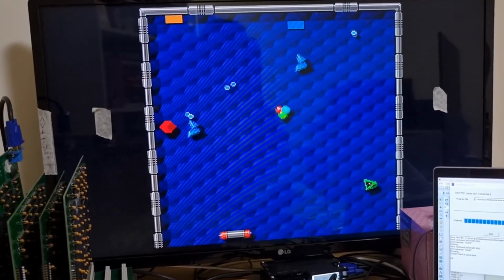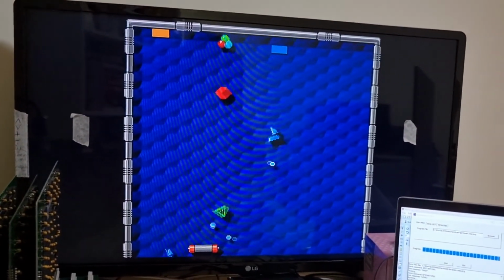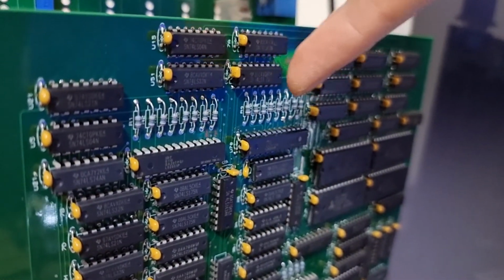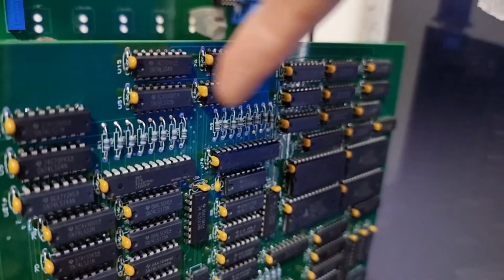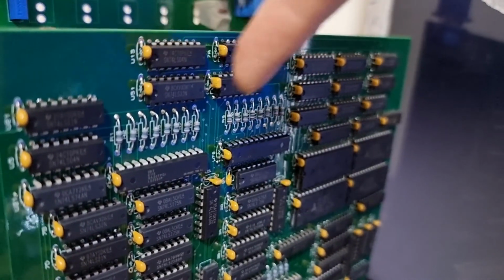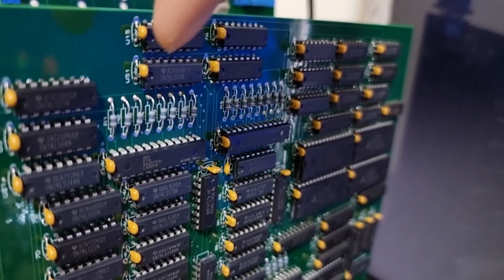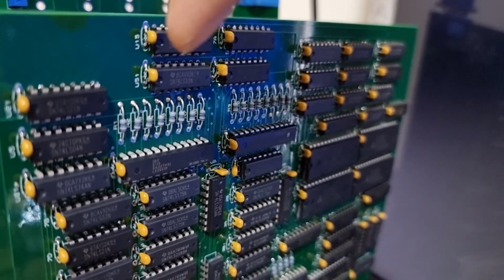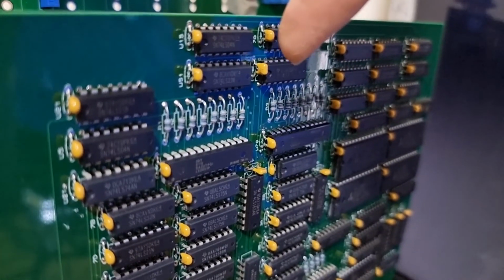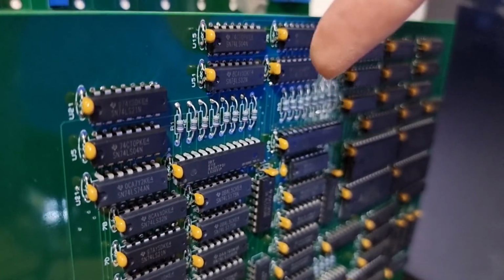And actually, something to note is that this sprites board uses different resistor pull-up values for the scanline RAMs here. I lowered the resistance initially. I think it was something like 5.6K or something like that. I'll have to check on the schematic in the source control to see exactly what it was.